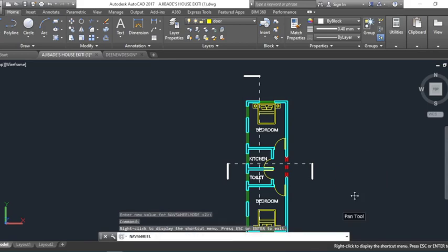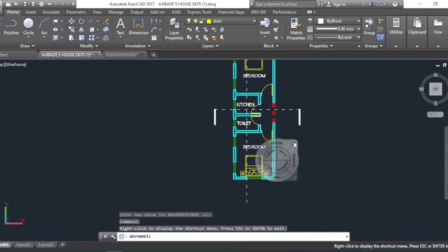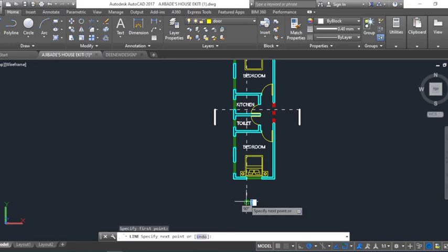Then same thing applicable here as well. Just pick my line. Then it has to go to the same direction. 1 2. So what this direction of lines means is, whatever I will be cross-sectioning will be facing this, it will be showing what is on this side. And this horizontal line here, with the lines pointing downwards, means whatever my cross-section will be showing, it will be reflecting what is downwards. So if that is clear.